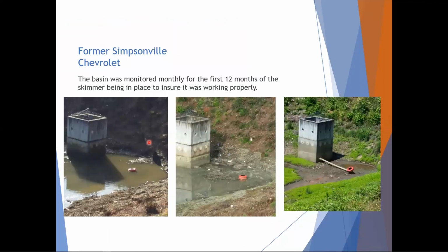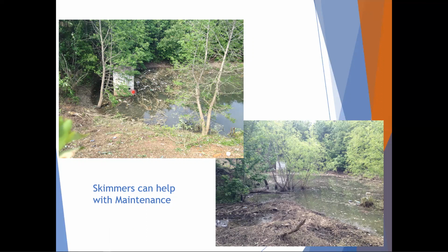So I'm going to back up. On this basin, you can see these orifices here, and you can kind of see it down here, but it looks like it's kind of drained out. But the only holes we could see were these that were like 4 feet above the bottom of the pond. When we got into doing some digging on it, it turns out that there's supposed to be a 2-inch orifice about 10 feet below these. And again, they're about 4 feet above grade. So that means the 2-inch orifice is 6 feet below grade, and it had filled up with that much muck and junk and trash over many, many years.